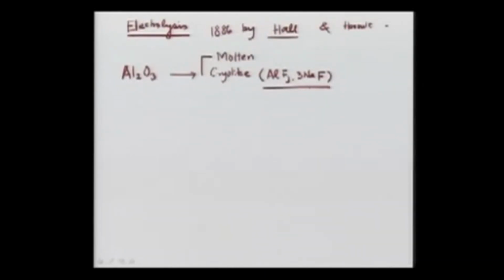The interesting part is that this Al2O3 melts at about 940 degrees Celsius, and then in this molten cryolite the Al2O3 can be dissolved, and then we can run through the process we call electrolysis. Then let's talk about the electrolysis process. Al2O3 is in the dissolved form now, and we are going through the electrolysis process. It will produce aluminium, and it will produce oxygen.